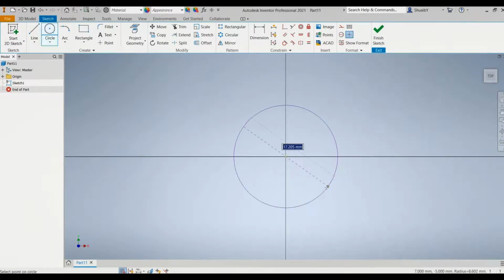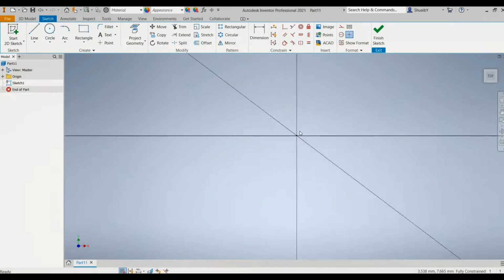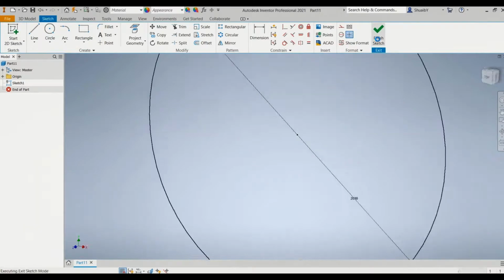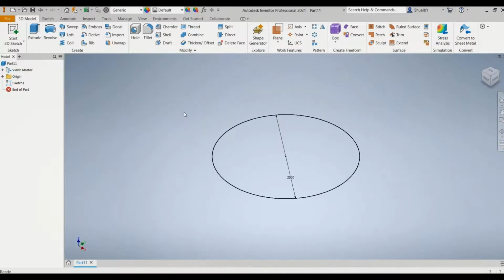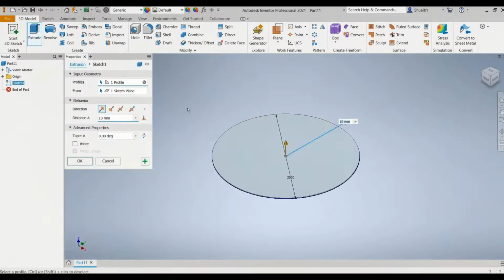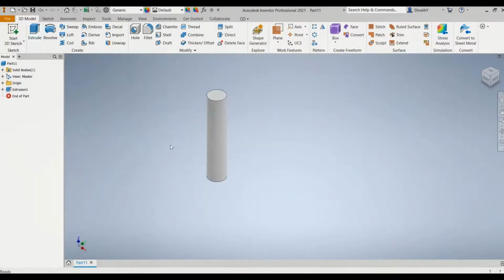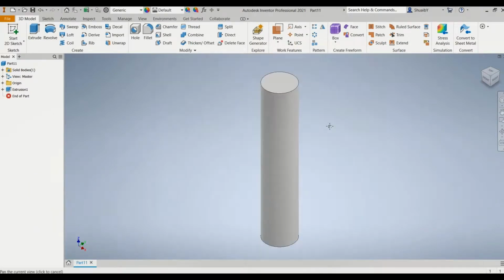And then we're going to create a pier. So I'm going to type in what I'm actually doing. So pier dia equals 2 meters or 2000 millimeters, and it's drawn the pier diameter according to what I want. So let's change the orientation. Again, this is like AutoCAD, right? Whatever you're going to see here. I'm going to extrude this. So let's make it 10 meters high, right? Again, with parametric behavior, you can actually edit this in Inventor, in Infraworks to adjust accordingly. So now we've got the pier or the column.